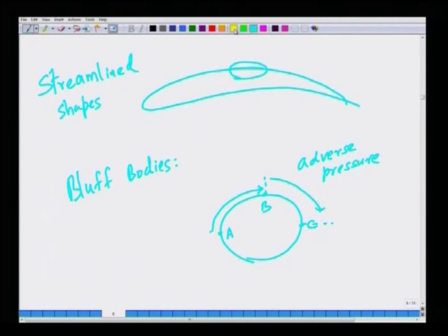So a fluid particle which moves from B to C moves by virtue of its kinetic energy, and that is being converted to pressure head according to the Bernoulli equation. But the Bernoulli equation does not have viscous effects. In reality, close to the solid surface there is a boundary layer, and there will be viscous effects which tend to retard the fluid particle.